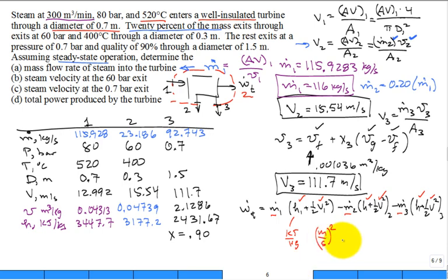If I wanted to convert units, I would multiply this one by 1,000: meters squared per second squared is precisely 1 kilojoule per kilogram, that unit conversion, which would then allow me to cancel these, and I would get the kilojoules per kilogram, both terms, add them together, consistent units. And if you don't do that correctly, you're only off by 1,000, which may not seem like a lot until you start talking dollars, right? And then it's real, right?